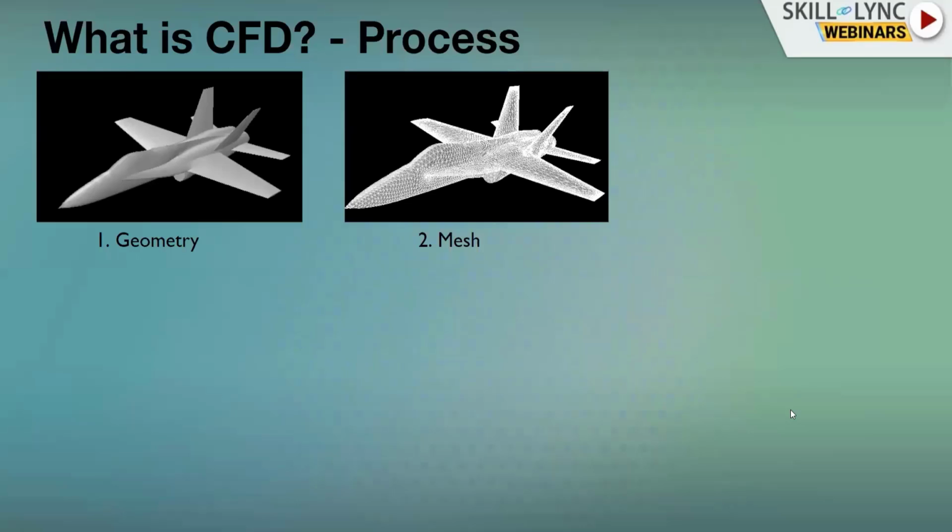The purpose of mesh generation is that the equations we saw in the previous slide are continuous. We are trying to solve a differential equation and an integral equation, which are continuous in nature. And those equations are valid within these small control volumes. From one mesh cell to another, there could be a discontinuity, or it could be different. This is called the weak solution. That is the primary purpose of generating the mesh.